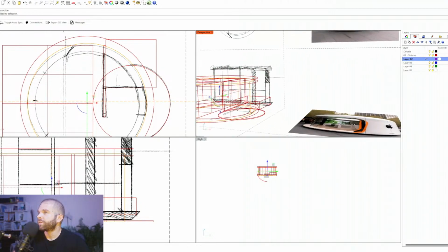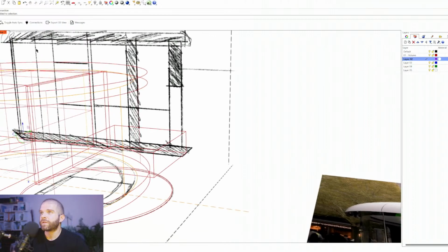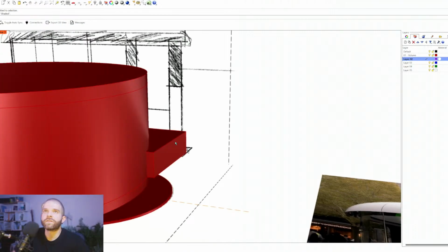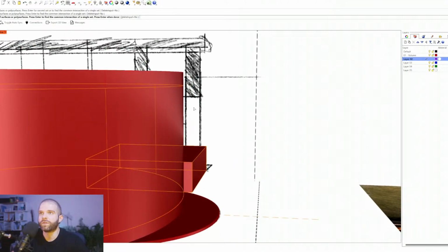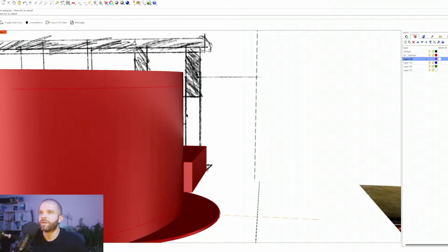So the Boolean intersection that I did, go here to shaded. If I do Boolean intersection, select first set of surfaces and polysurface, and it says delete input, yes. Delete input, no. Click there or do D, enter. I don't want to delete my input so I don't lose my inner wall, which is what just happened. All right, so there we go.